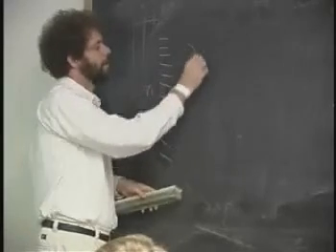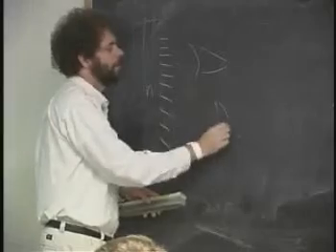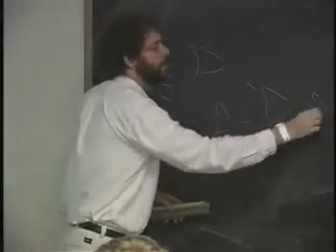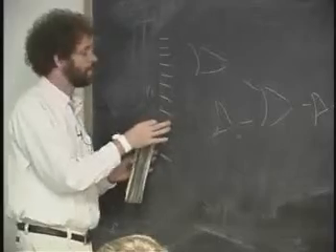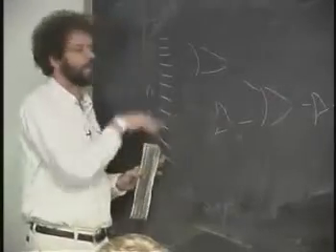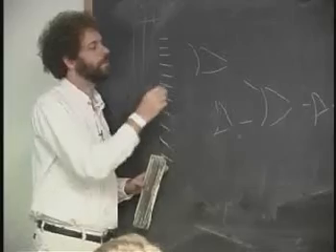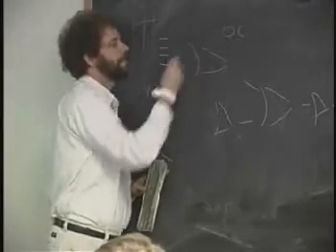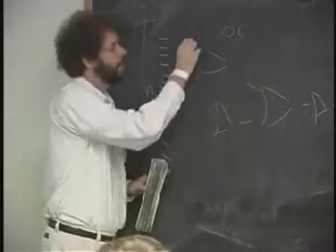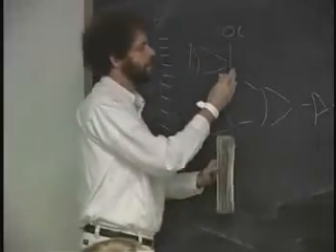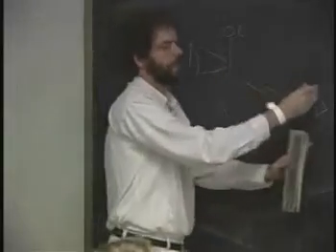The only way to do it is to build some type of tree. I don't know what the tree is going to be, but ultimately I have to do that because I need to make that bit sensitive to all of the bits here. And what does that mean? What's the order of growth of the speed of a circuit like this if each element has constant time? The bits come in here, they take constant time to go to here, constant time here, constant time here.